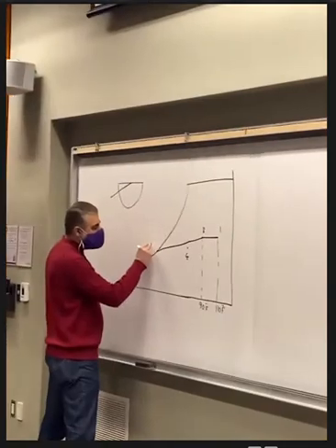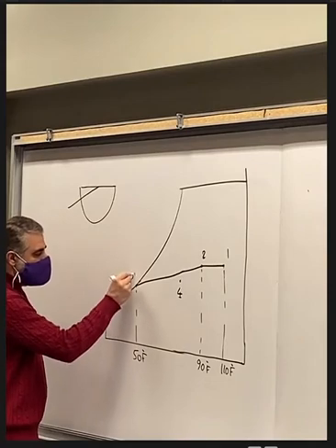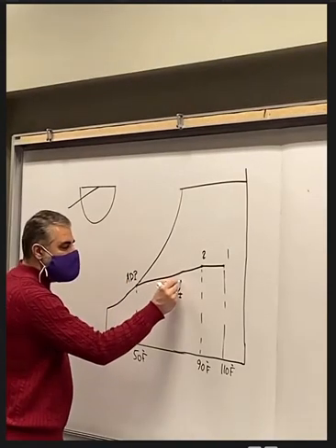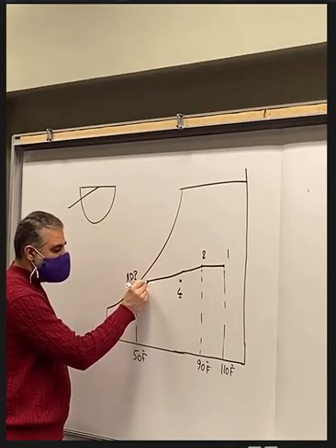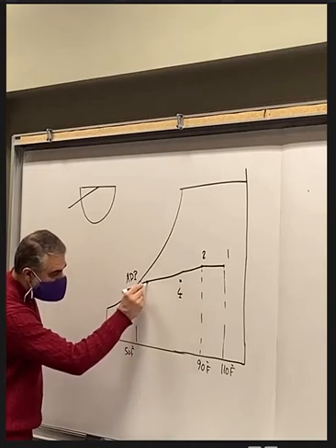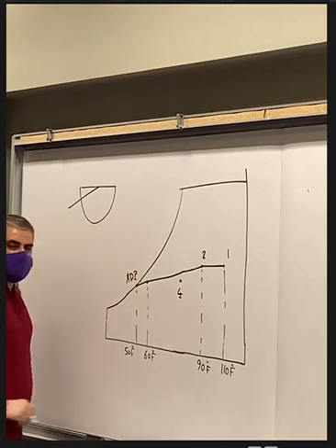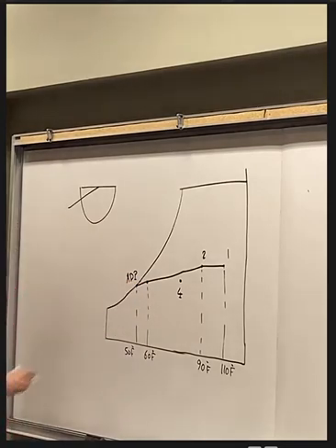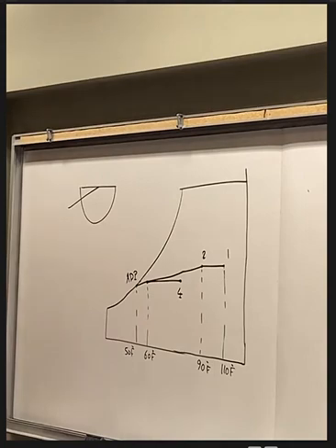So we have the cooling line. It will intersect with the 100% line at 50 Fahrenheit, which is the ADP. And the air will be supplied to the space at a temperature equal to 60 Fahrenheit. So this is the supply to the space. So that means we can supply air to the space by drawing the air conditioning line. So that's the complete psychrometric chart for this question.